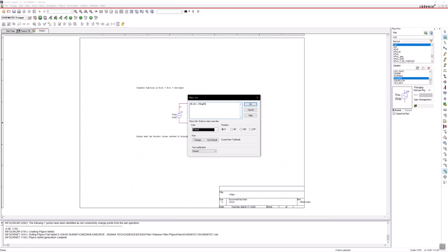and it's going to look a little weird here. It's hard to see in here, but I have vertical lines around the H at j omega. That means it's the magnitude. You might want to say absolute value, but it's technically a magnitude because we're talking about complex numbers. So it's 20 times the log of that. Because, again, we're in a log scale, so it would make sense to look at our data in a log scale as well. So that's what we have to do to compute it by hand.